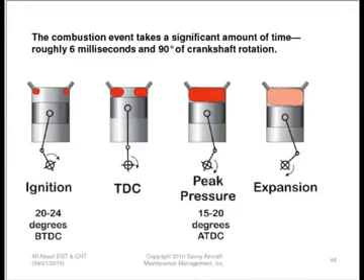The way a combustion event works, first of all, it's not an explosion. It's a smooth burning event that normally takes a fair amount of time, roughly 6 milliseconds or so each time it happens. It starts at typically 20 to 24 degrees before top dead center when the spark plugs fire, and then the combustion continues to progress as the piston gets to the top of its travel and then starts back down into the power stroke. Normally the combustion event is fully developed and reaches its peak pressure at somewhere between 15 and 20 degrees after top dead center, and then gradually starts to cool down as the piston goes down and the gas expands and cools.